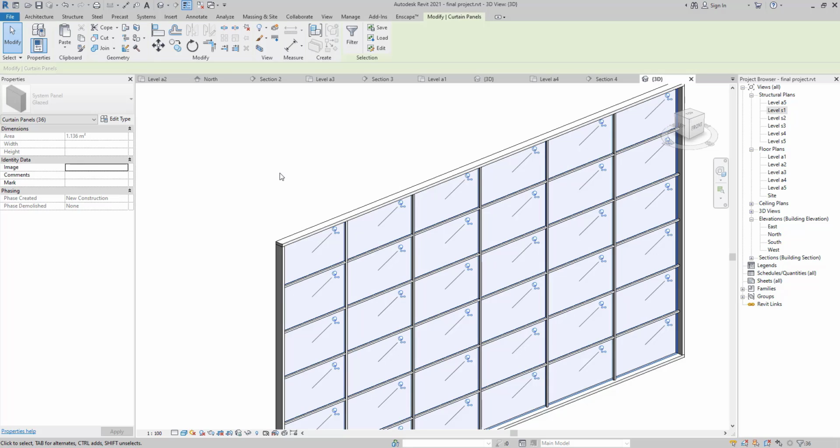But what is the difference between changing here and as a default? It means that you are going to change it individually. Later you can change it again individually. For example, if you change all of them to the wall, and after that you want to have, for example, 4 of them as glass, you can just go click on those 4 and change them to glass, and your default is going to be changeable. But if you change as a default here, all of your panels are going to be changed as a default to that certain material, and it's going to be a different process to choose the other.